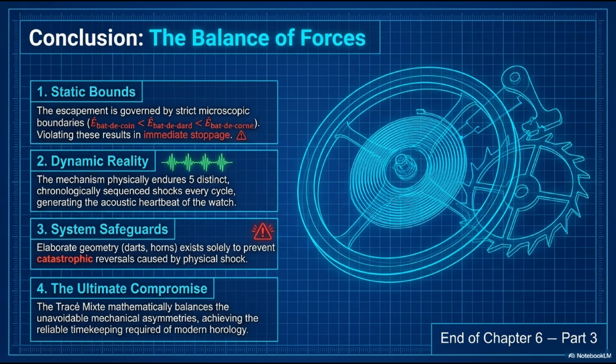This slide concludes part 3 with 4 synthesis statements that each capture a fundamental truth about the Swiss lever. First, static bounds. The escapement is governed by strict microscopic boundaries: ébat de coin less than ébat de dard less than ébat de corne.